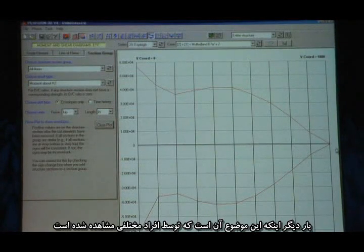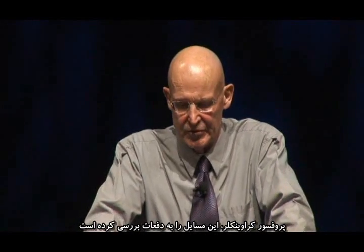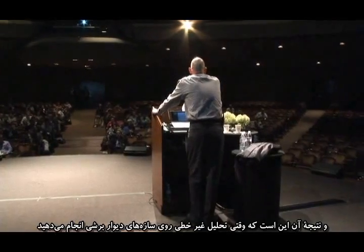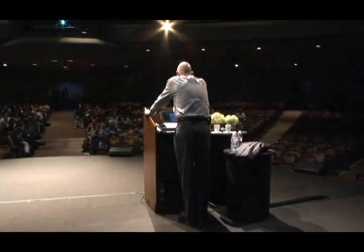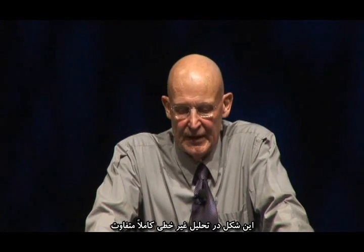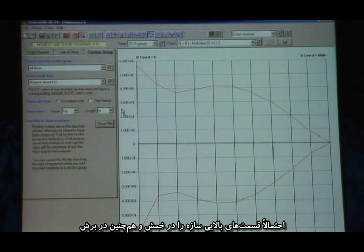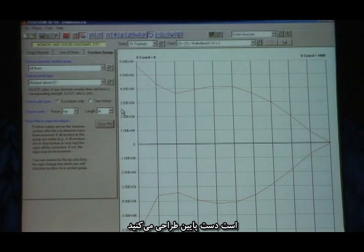So once again, the indication is, and this has been observed by a number of people, Professor Krawinkler has observed this many times in recent years, that when you do a nonlinear analysis on a shear wall structure, some strange things happen, and the shape of the moment envelope that you get is quite different in a nonlinear analysis than it would be from a linear analysis. The conclusion is, if you do a conventional code-based design where you use linear analysis, you're likely to under-design the upper portions of the structure in bending and also quite likely in shear.